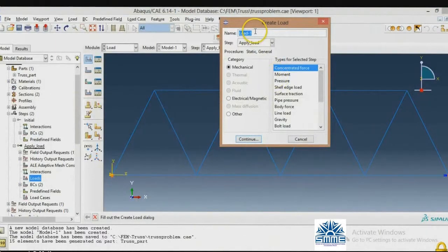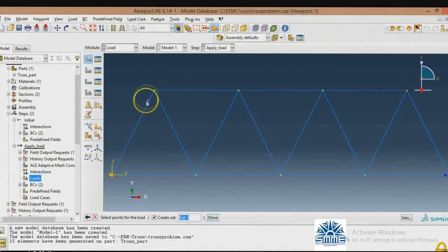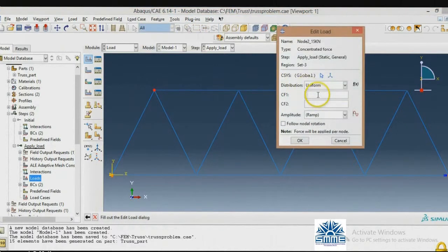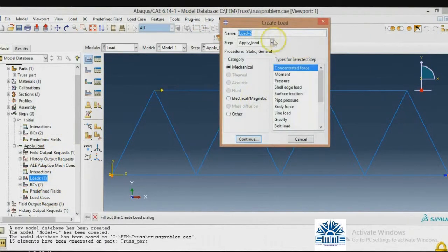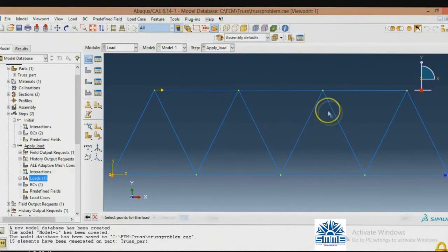It's node 2, load 15. That's its name. The computer doesn't know that it's 15 now. Right now, just for our understanding, it's on this edge. Say done. This is what the computer wants to know. It's 15 in the x direction, positive direction. Okay, and create one more. So repeat 4 times. It's node 3. We have 7 or 5, I think. Yeah, 5 kilonewton. Okay. Say done.